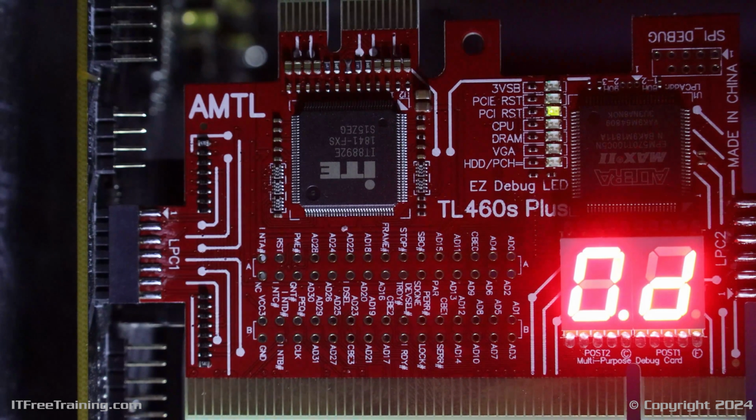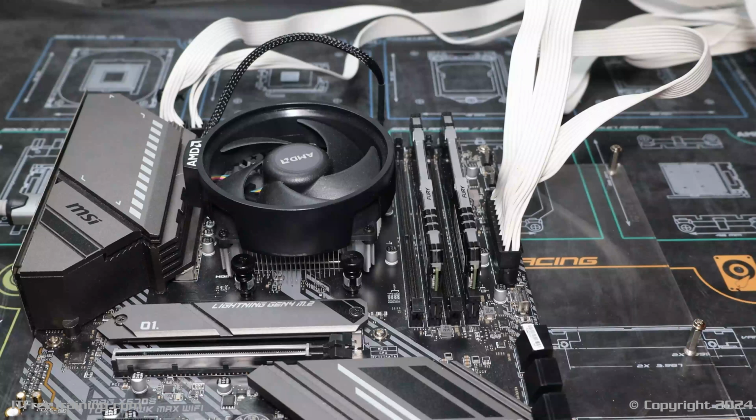Manufacturers don't always release up-to-date postcodes. However, a quick internet search for the postcode C5 for this motherboard manufacturer shows a lot of people reporting that this problem is memory-related. Although the postcodes are good to have, they don't mean anything unless you can figure out what they mean. Hopefully, the manufacturer of your motherboard has released the postcodes. This is the main reason I treat them as a last resort. They can be really helpful, and at other times, if you can't work out what the code means, it is not helpful at all. Since it appears the problem is memory-related, I will remove one of the memory modules.